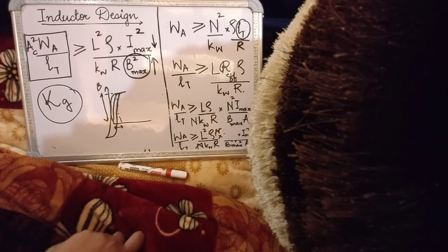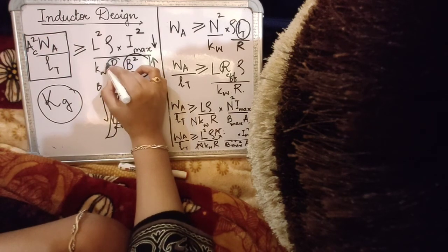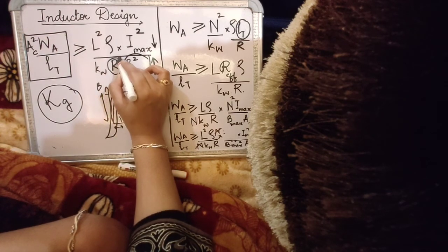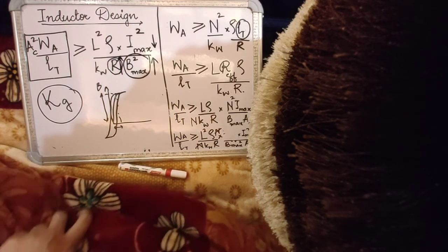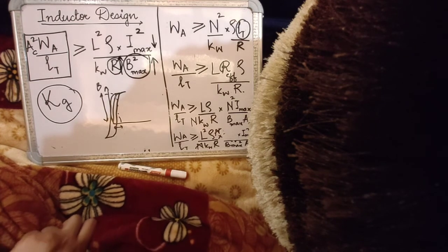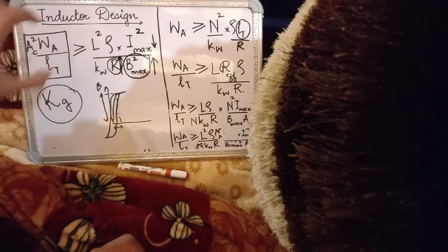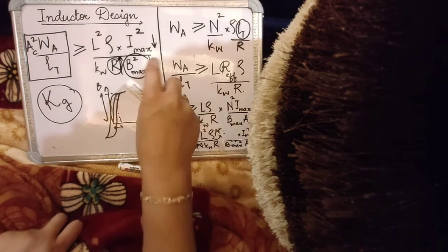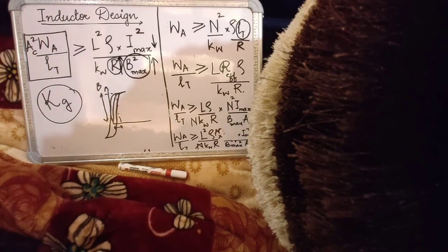And if you want that to happen, then of course you will have to increase the reluctance, only then will it tolerate more current. Another way of miniaturizing the core is to allow greater losses in the core. Let there be more effective resistance of the winding. Then in that case also you can effectively reduce the size of the core. So all these will give you insights on what to increase and what to reduce in order to get the optimum size of the core.